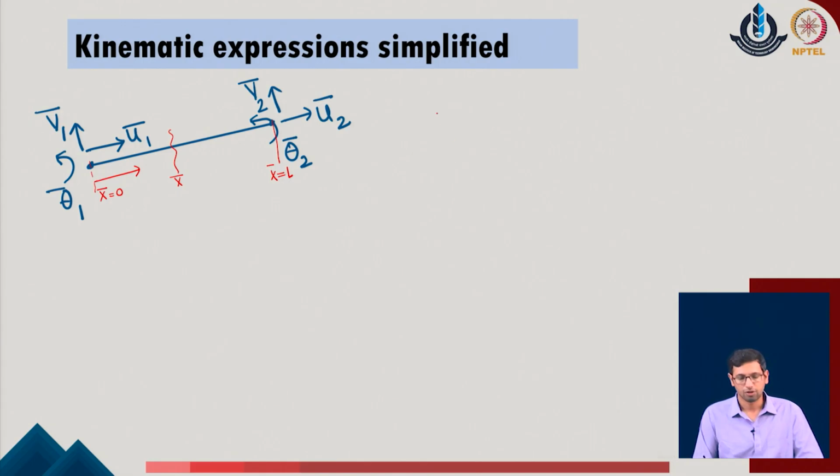So, if I want to go with the value of u, which is the in plane displacement, again I define it in the local coordinates, as I am looking for the answer to be dependent only on these two parameters of the system, which are u 1 bar and u 2 bar, I can approximate it with respect to a simple linear function. What is the intention of it? If I have 2 points for which I want to express the given function, I can only generalize a standard linear function for these 2 points based upon the available set of equations.